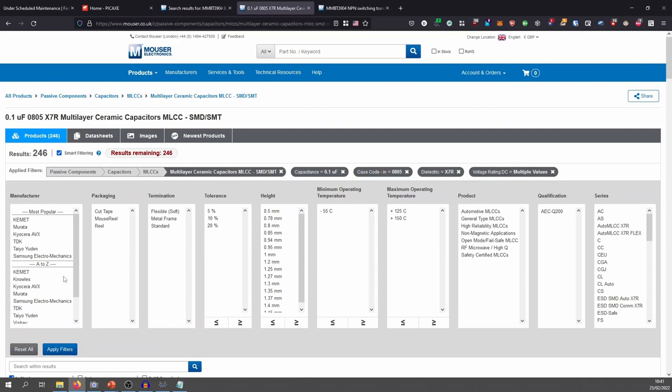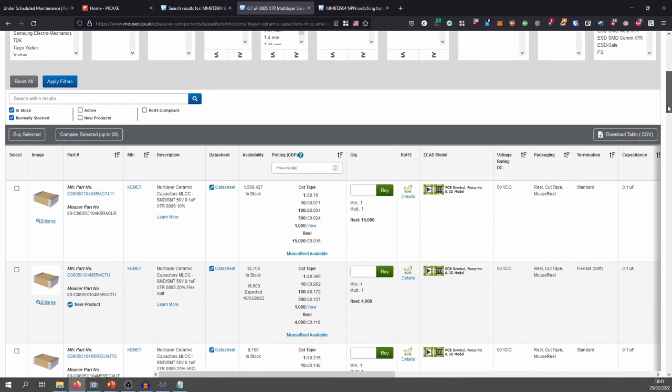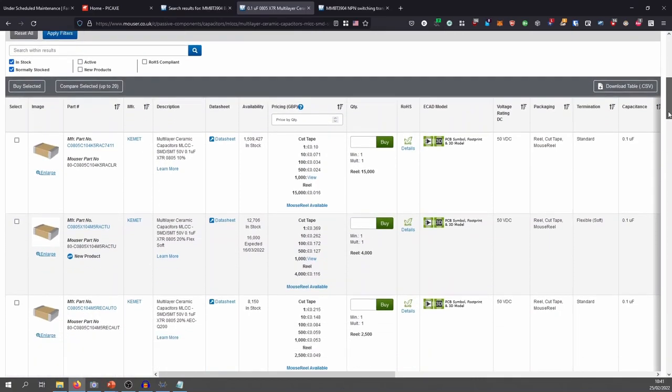There's also the metric ones which use the same dimensions, and it's really confusing. It's like an 0805 imperial, like an 0603 metric. There's also an 0603 imperial. Is it the same across all the suppliers, or is it because Mouser is American that they use? No. 0805, 0603, 1210, 0402, 0201. They're all standard electronics package sizes. And you typically do use the imperial version. They're all based on thou, mil, which isn't a millimeter. You just get used to it.